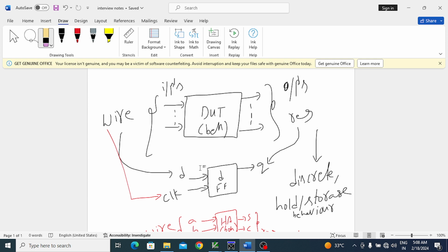If there is no temporary variable and I am using the output port on the left hand side of the statement in the procedural block, then I will write reg for that output port. Anyhow, the question is, why wire for the input ports and reg for the output ports.